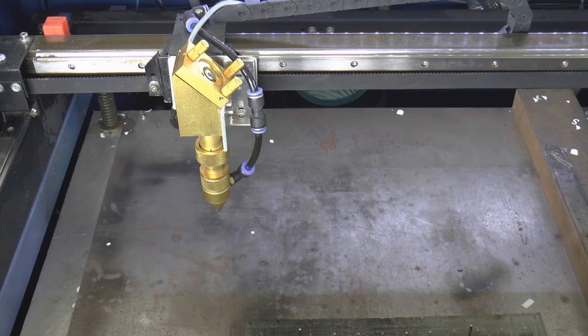But with the absolute program, if you just draw a program starting at, say, your start position, say 100, 100, then if you drop that program into the machine and just literally run it with a frame, it will stop the head at 100, 100, and you can then press the origin button. Job done. You can then swap it over for your running program that you want and run that program from 100, 100.